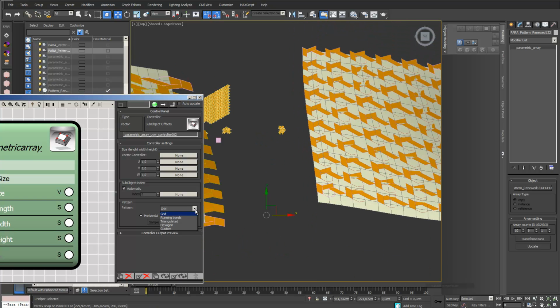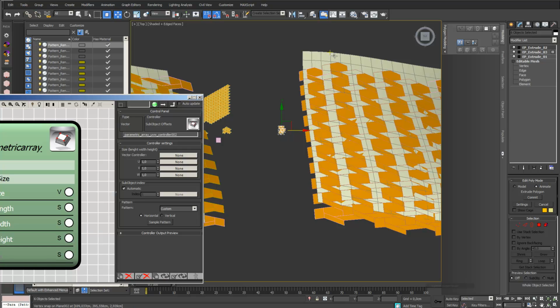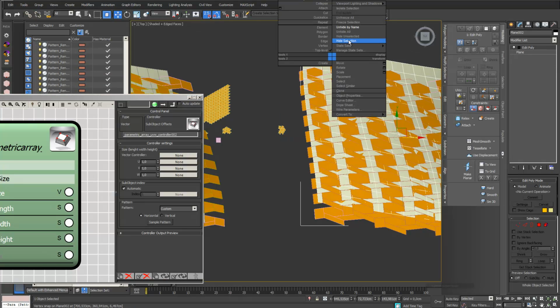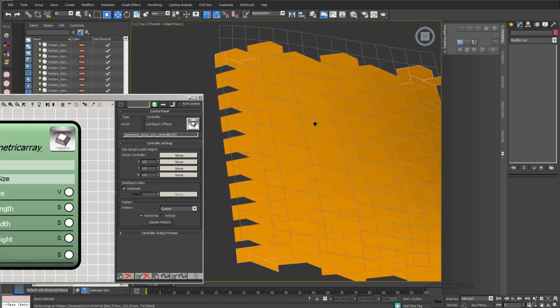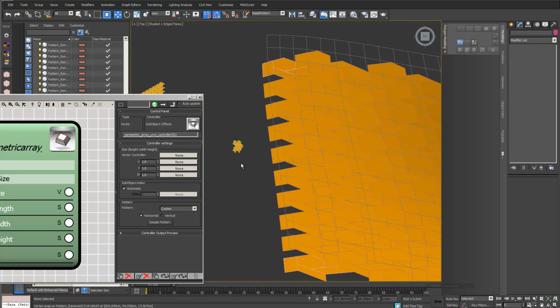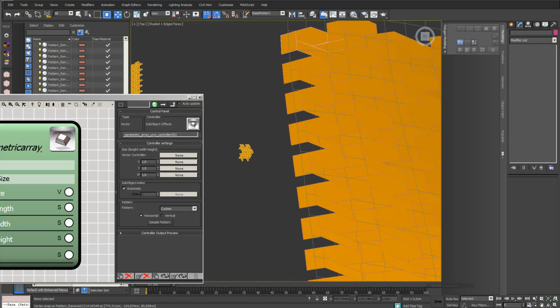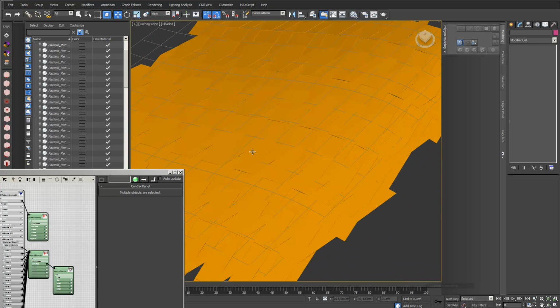And if I go now into custom and choose my pattern like this and go into sample, then I just select the pattern 2x3, confirm, and I update the whole thing. Switch off my hide selection of my object, and here we go. Also, this looks really good. And so just be aware of what you do with your pattern, that you understand this part. This is really important. So let's see what you can do with your surface cladding in detail.